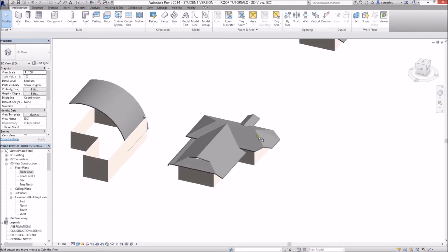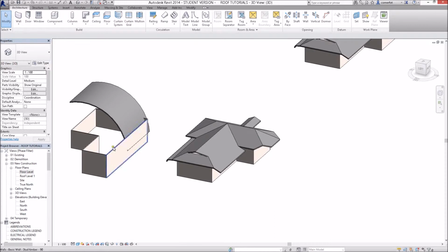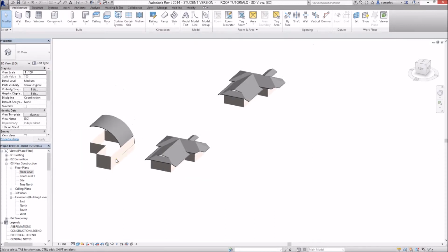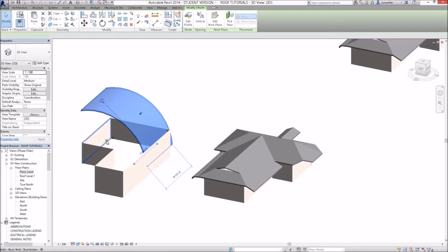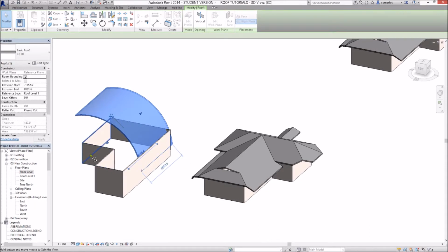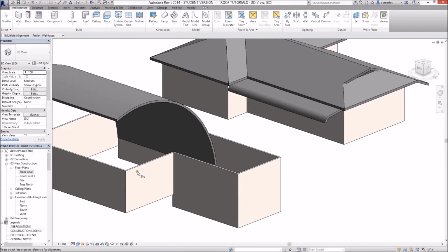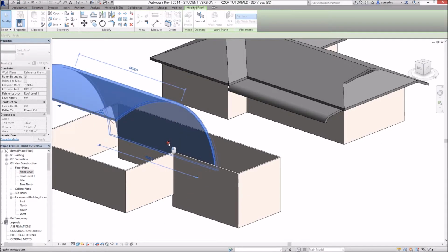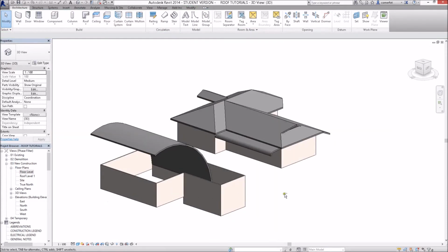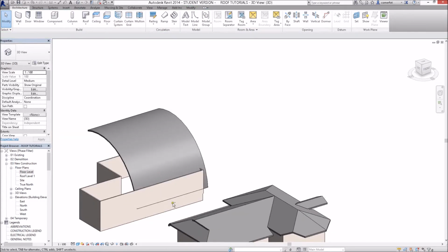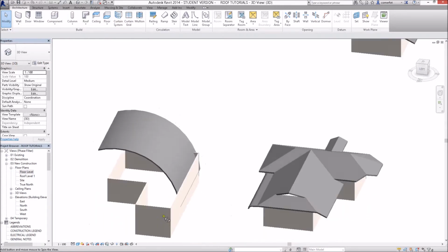Now if I set another roof up to cover this other shape here in the front, and that roof there also, we extend that, it'll probably come to this point through here. Now I'll align, and I'll use that wall surface to align it to that roof surface, and then once again use the blue grip just to extend that out by some known distance that you give yourself for a roof overhang. Okay, so